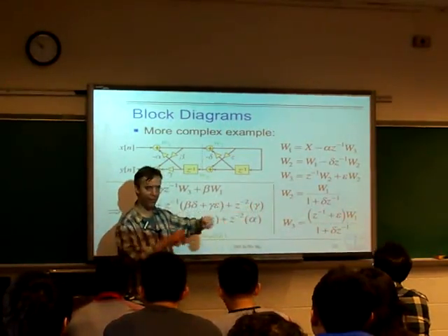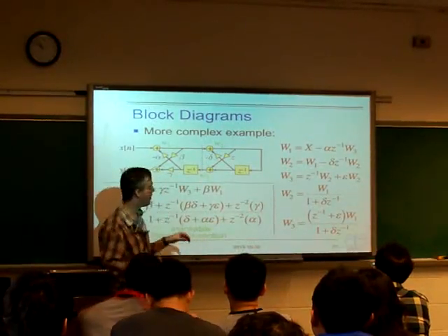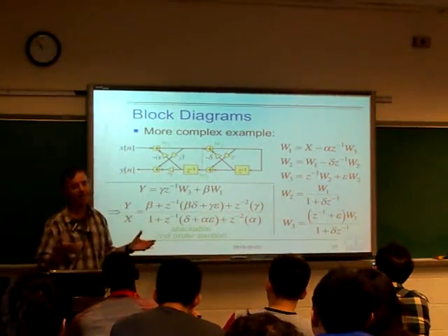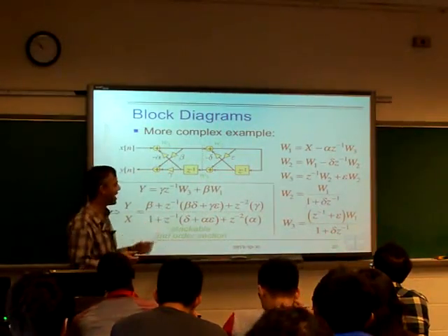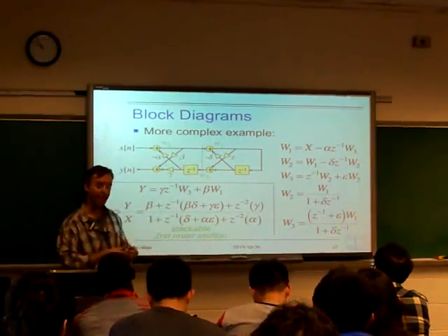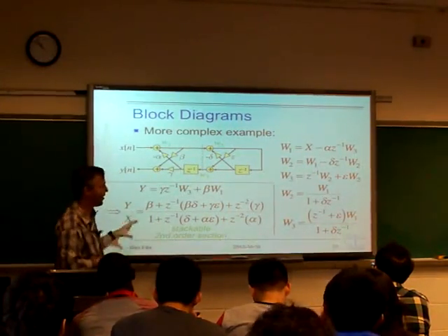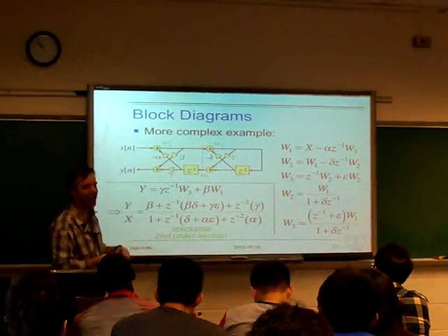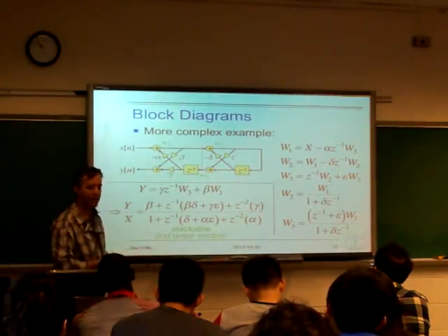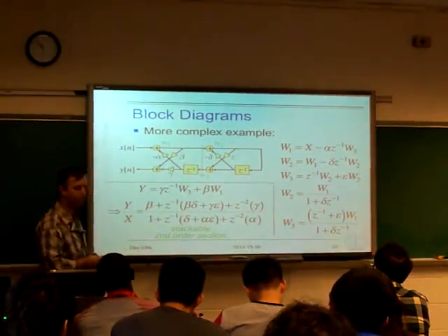In a higher order system, if you've just got the fully written out polynomial, it's hard to see what the magnitude of the individual poles are going to be. But here we have these things separated out, and so we can guarantee that all the poles are stable. That's where I've seen it used: if you use a lattice filter, you can make sure that you don't accidentally end up with a filter with some unstable poles in it. But that's not been explained; I'm just saying that's where you may come across it. It's got some nice properties in terms of stability and implementation.